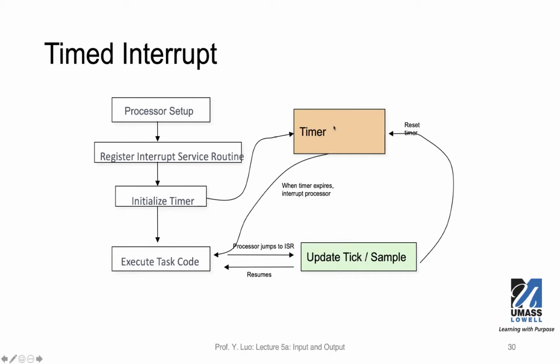So the reason we have different colors is because this timer unit is really hardware-based. You are not writing code to update the counters in the timer. This is done by hardware internally as a part of the microcontroller. This is the software code you will write as the ISR for the timer interrupt.